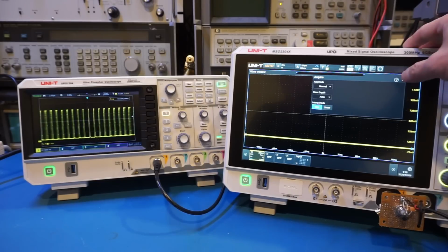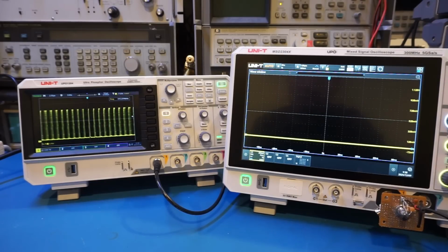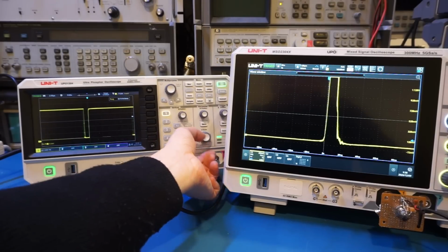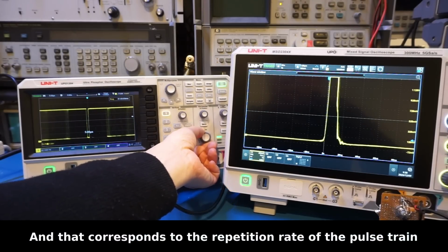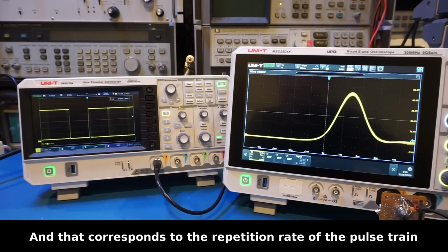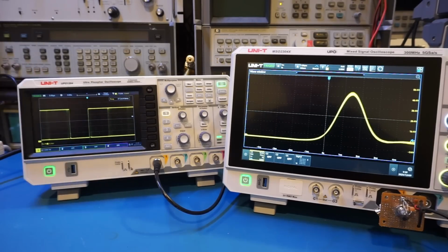And let me actually enable the Avalanche pulse. You'll see the triggering pattern will change. And now we are triggered. You can see that the triggering frequency actually changed to about 40 kHz. So that's the triggering signal observed on the oscilloscope.